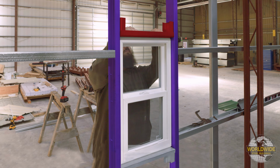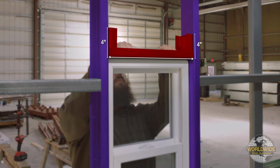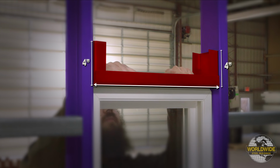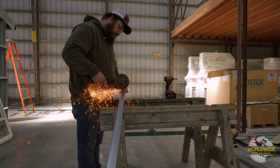For the header and sill, you will use a similar method. Measure the distance between jambs and add 4 inches to each end for the tabs. This will be the overall length of the sill and the header. Measure and cut 2 pieces of track to this length.